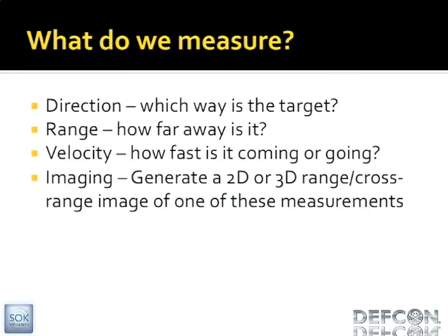And when I say range and cross-range, what I mean is, in the radar world, if you take a picture of this wall, for instance, or that wall, whatever, your two dimensions are up and to the side. They're both perpendicular to you. A radar flips that 90 degrees. So one of your dimensions is range, which is how far away the thing is, and the other one is in some other axis. So it's cool because you can look from the side and then get kind of an overhead view of what something looks like.